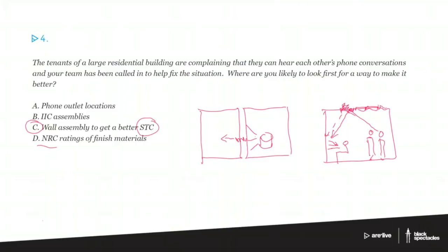And walls with pretty terrible sound transmission numbers are going to be down in the kind of high 30s, like a 38 or 39. Ones with really high might be up in the high 60s, something like that. Sort of typical for a demising wall you'd be looking for would be somewhere in the high 50s up to 60 in that range.